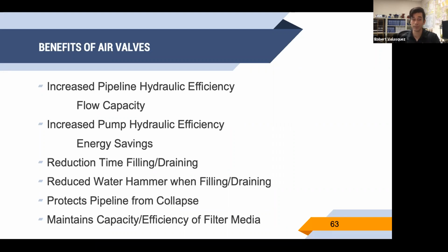A little interesting concept I remember hearing from an engineer was that pumps are not creating energy, they're converting energy. They're taking the electrical energy and converting it into hydraulic energy, the flow of water. So if you can get more flow by reducing restrictions, you use less energy.